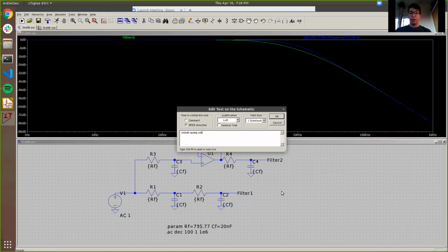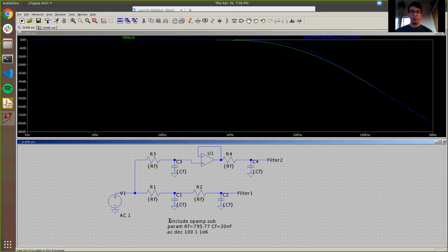If you end up taking circuits with Brad, you're going to have to include his special library that he's made for class. So you're going to end up using this at some point. If you decide to import a component that's not already in the LTspice library, you'll have to include that component. Some manufacturers will include a spice model for their components so you can more accurately model what's going to happen if you're using that very specific component. So we're just going to hit OK and just set this down somewhere.